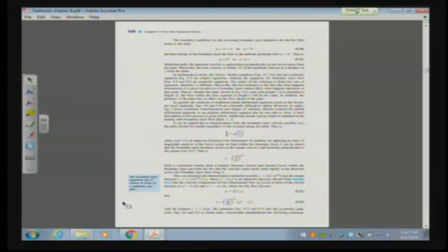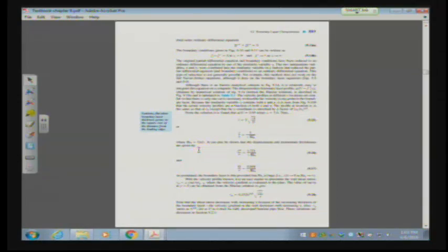these equations, and we conclude for this little part that the boundary layer equations can be written in terms of a similarity variable. So what we're doing really is talking about how we're going to solve those differential equations. All right, so we have a specific condition here where we have to take into account what Reynolds number looks like for laminar flow and for turbulent flow. And of course, it gets much more interesting for turbulent flow, but the laminar flow equations are somewhat easier to follow.